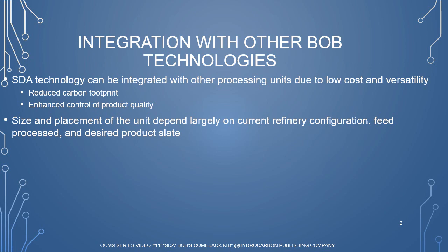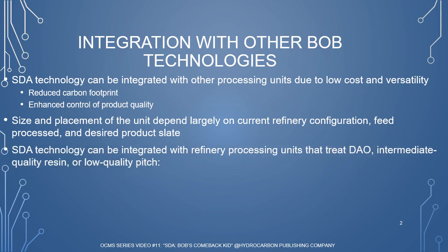Solvent deasphalting can be integrated in a number of flexible configurations with a range of refinery processing units that treat the high-quality DAO, intermediate-quality resin, or low-quality pitch, such as the coker, visbreaker, gasifier, resid FCC, resid hydrocracker, etc.